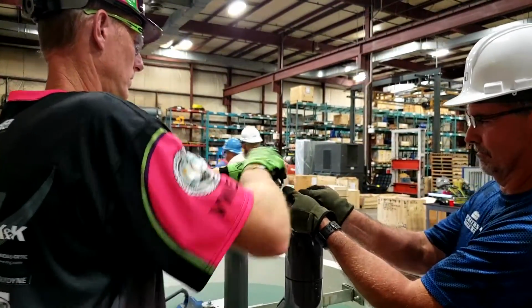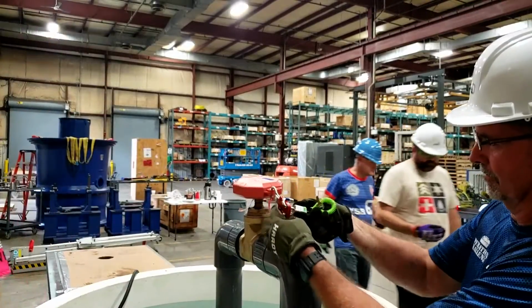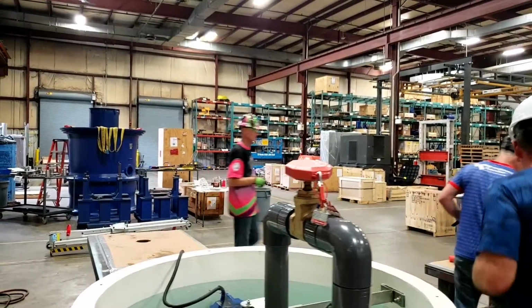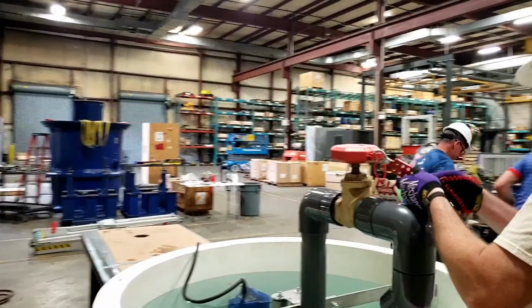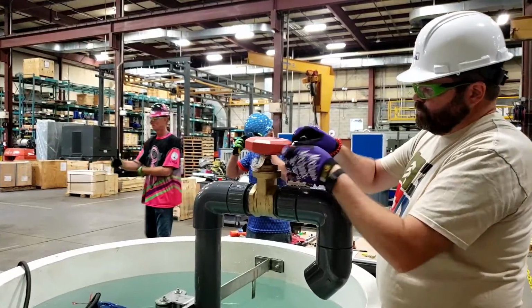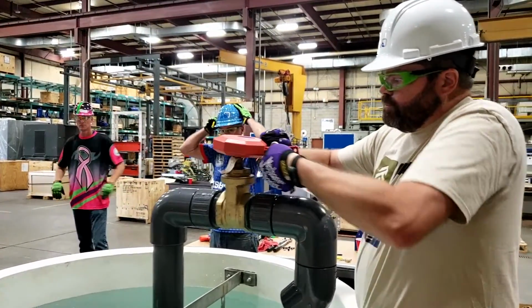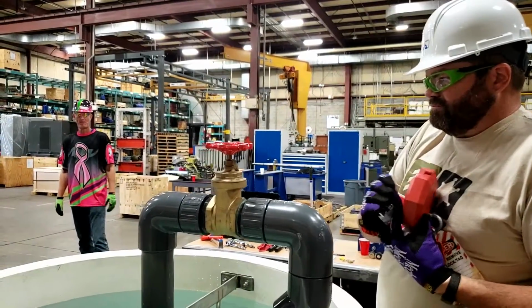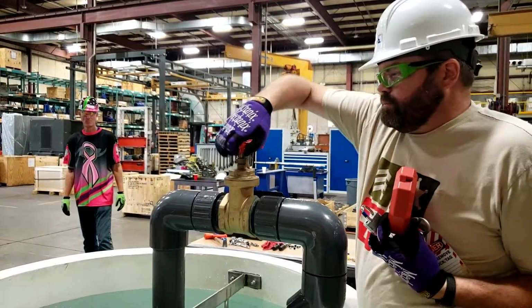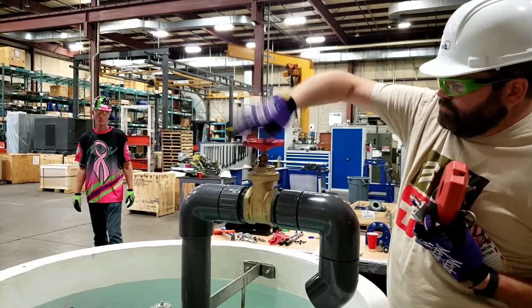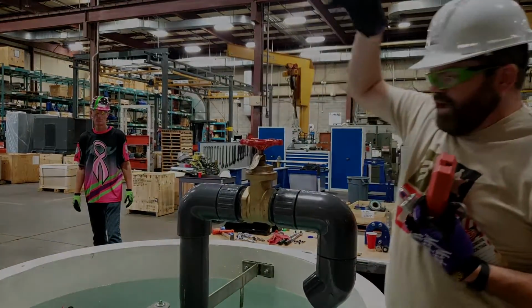Each individual that is locked out is responsible for removing their own lock. You may not remove the lock for another team member. The safety supervisor shall be the last one to remove the lock. This task must be completed prior to turning the pump 1 and pump 2 disconnect to the on position. Valve is open.